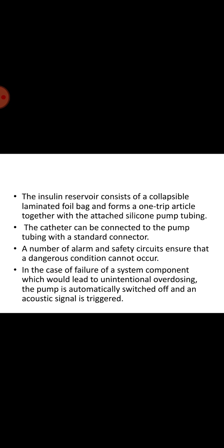Manufacturing tolerances of the pumping head can be limited to plus or minus 1% with proper pre-production control. And for manufacturing tolerances of the pump tubing, the internal diameter, wall thickness and hardness of the pump tubing have an effect on the supply rate. The error caused by the tubing could be of the order of plus or minus 4%. These errors are usually tolerable in patient treatment, since an individual dose is determined with a particular dosing device and a particular tubing. Thank you.